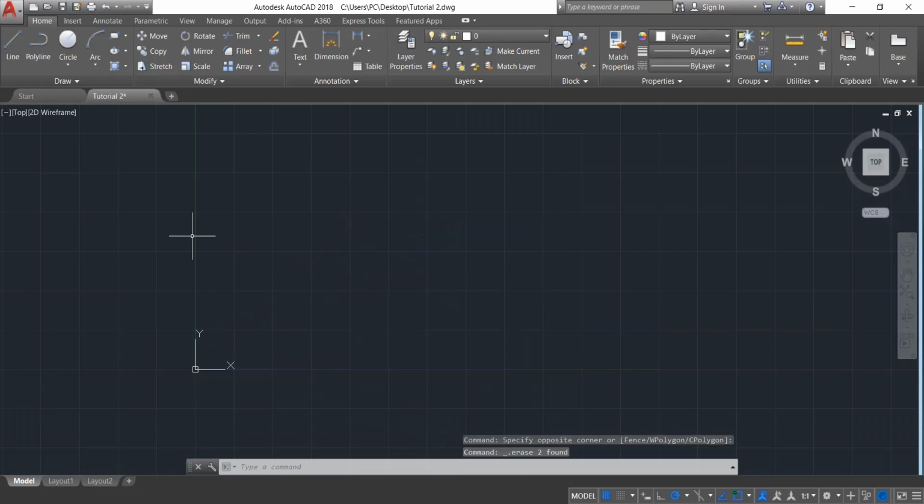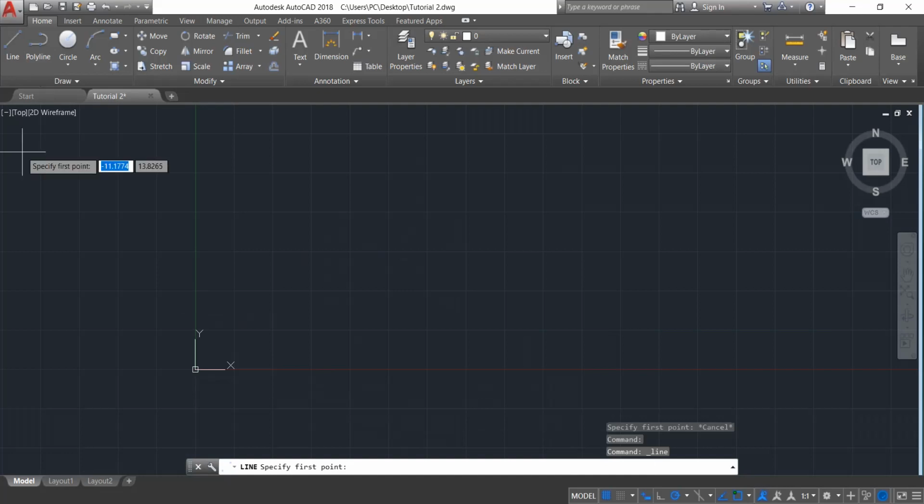So we're going to draw a line again. Select line. Yeah, so you may say the process looks hectic. How will I get a full drawing? Sometimes it's not that you should go to a particular point. You just want to formulate a figure at a certain distance, but you can start from anywhere. So when specifying the first point, instead of typing 0, 0 for the coordinates, I can just click where I want it to start.